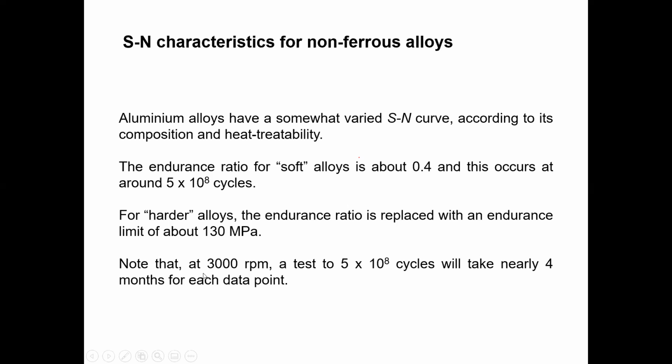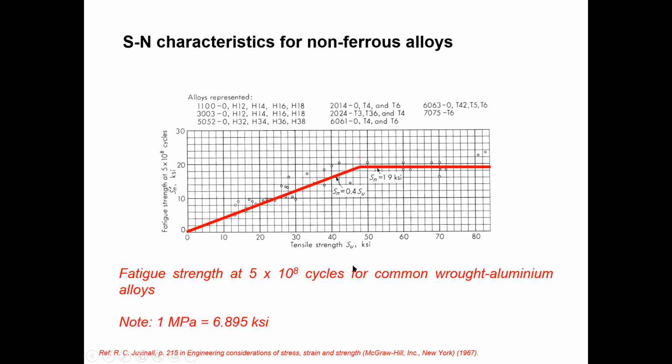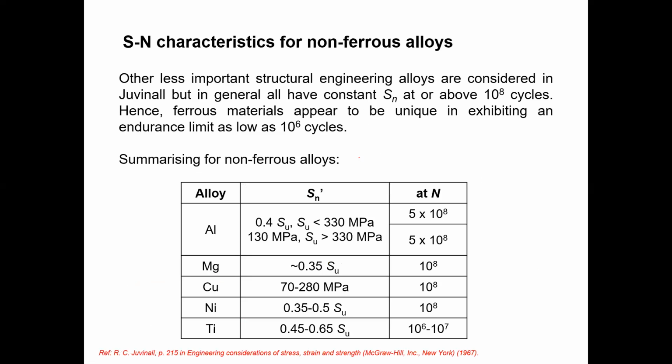Okay. So you can see here. I'm not going to go through that one too much. So the harder material has different values like that. So again, this is aluminium alloys. You can see the SN curve, and different alloy materials have different endurance limits and different fatigue lifetimes. So this is the endurance limit, and this is the number of cycles.